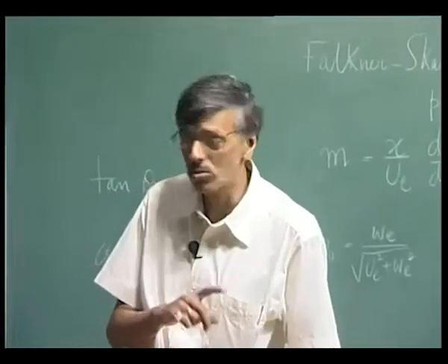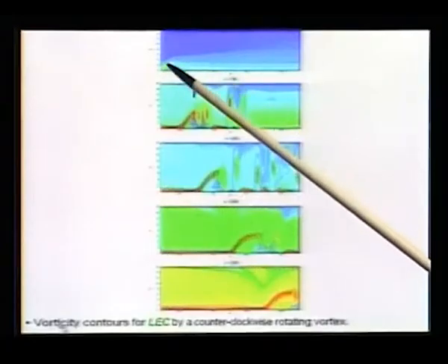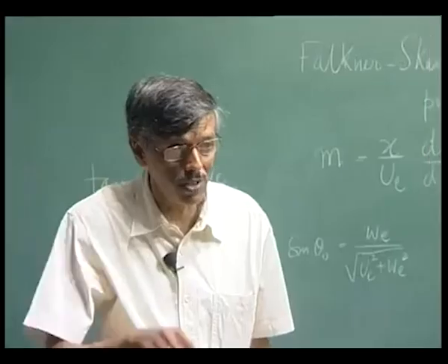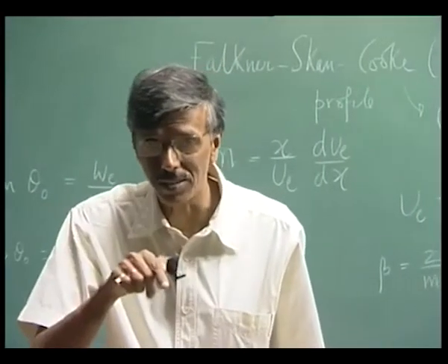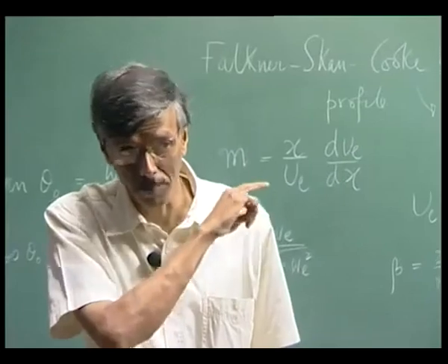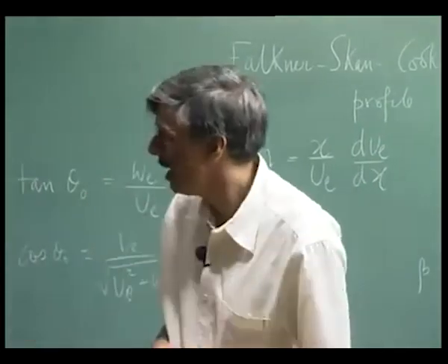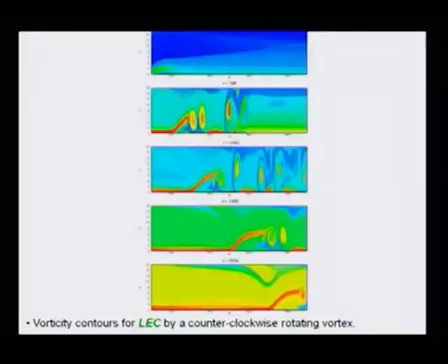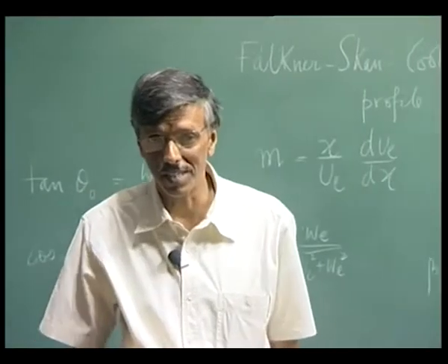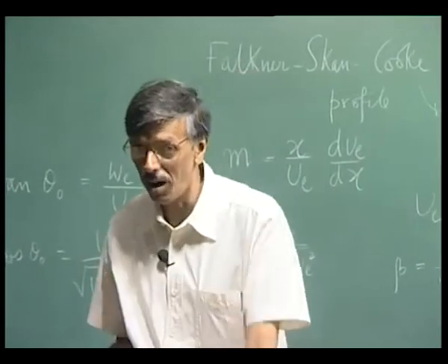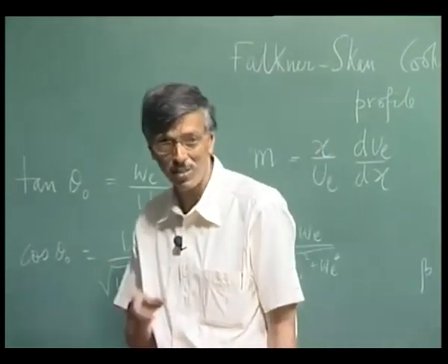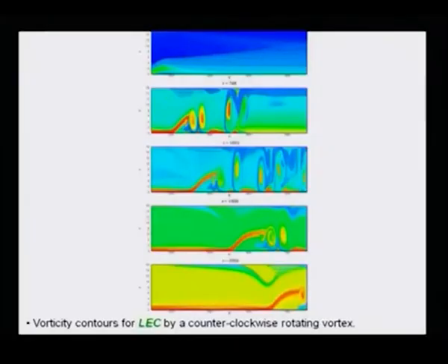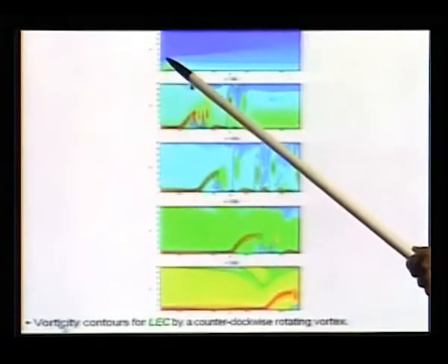Of course, it does so through the inflow boundary condition and the top of the computational boundary, where you have some imposed condition that shows the effect of the approaching vortex, and you can already see a bulge there indicating the flow is being affected. And that answers your question whether we have a constant shear layer thickness or not. It just simply starts affecting it somewhere here.